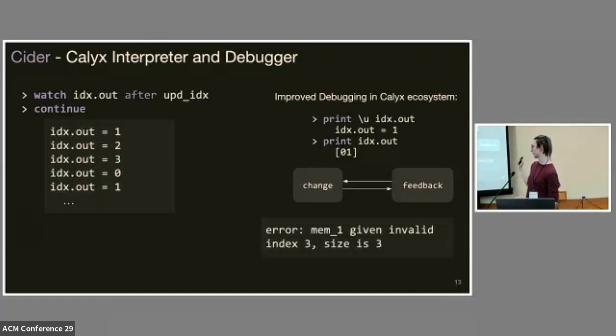And most excitingly, at least in my opinion, we're able to address undefined behavior at the level of the Calyx semantics itself, as opposed to allowing things that Verilog says are okay, but we really don't want in the language semantics. So for instance, memory addresses: you can actually provide invalid indices to memories in Verilog, and that's okay for some definition of okay. Whereas in Calyx, we really want to outlaw that entirely. There's no reason your accelerator generator should be misindexing memories.